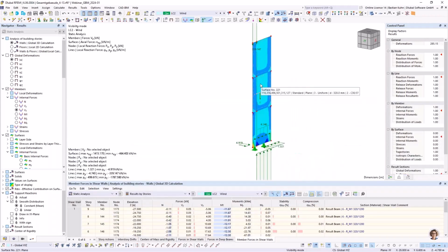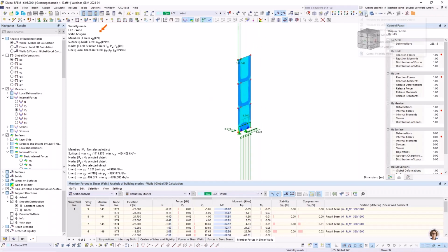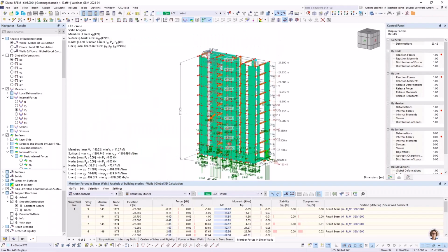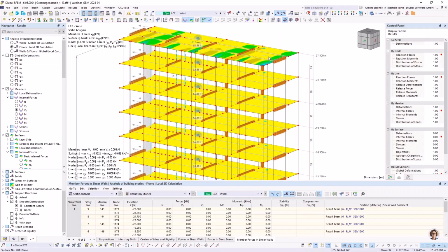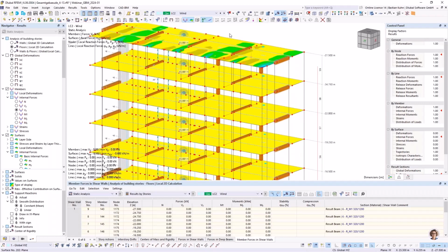Yeah, this is the advantage. Let me take a look. I probably have missed some points, but I can't remember them now. Yes, one thing. If we cancel the visibility mode and take a look at the floors again, you see also an effect. NXY in the floors is nearly zero, even though I have such a high horizontal deformation. Why is it the case? Because I'm calculating only 2D for the vertical approach in this here. And if I go to walls, it's different.